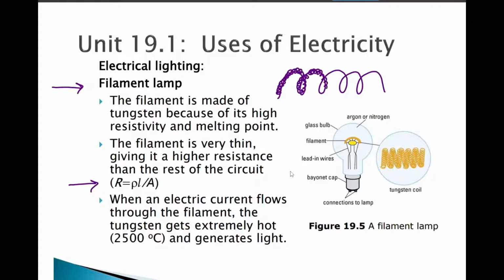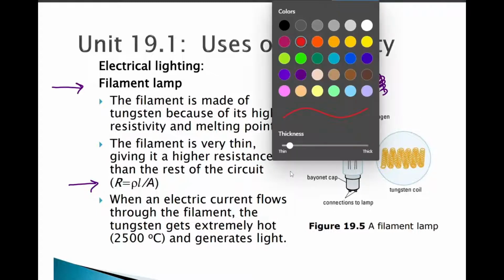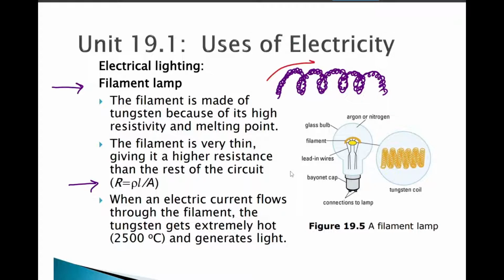So if we increase the length of that wire greatly, then the resistance of that wire increases greatly. And as a result, if the resistance is too high, then whatever amount of current that tries to pass through it will generally produce a heating effect. That heating effect eventually, when exaggerated in that certain situation, becomes so high that it starts glowing